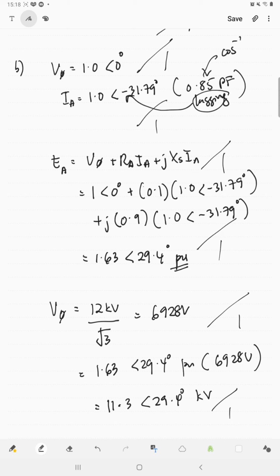That's why it divides by itself, and that's why you get 1. The same thing happens with current. So if you are computing in one single phase circuit, you will always have V is 1 and IA is also 1. The degree of lagging or leading between them will depend on the power factor.